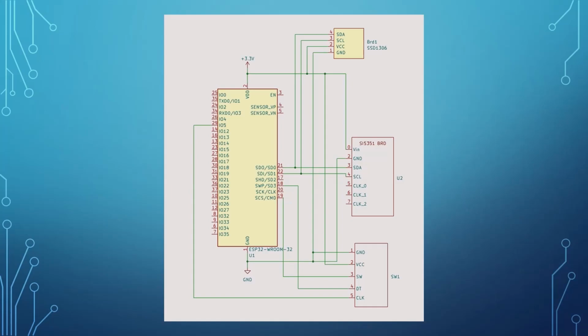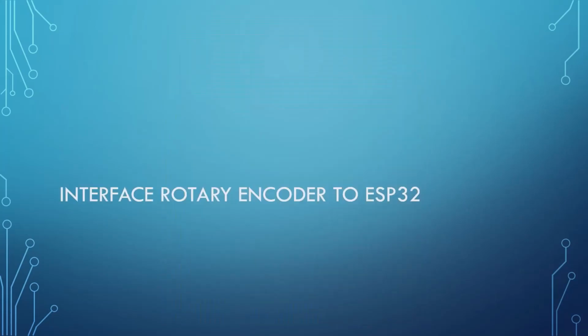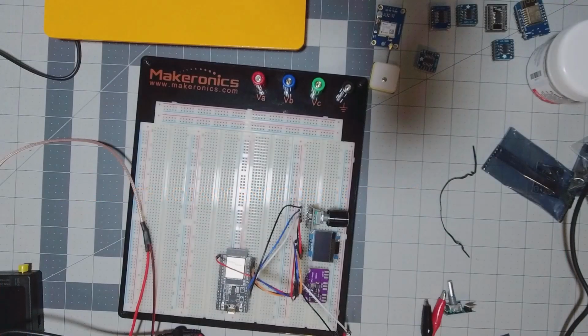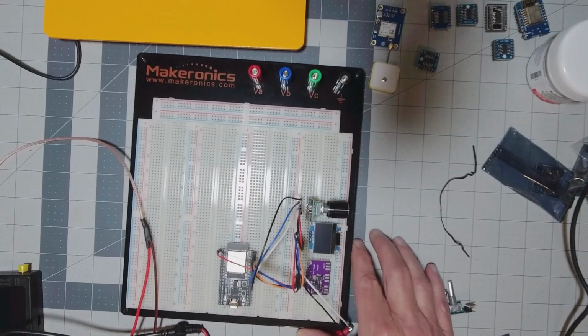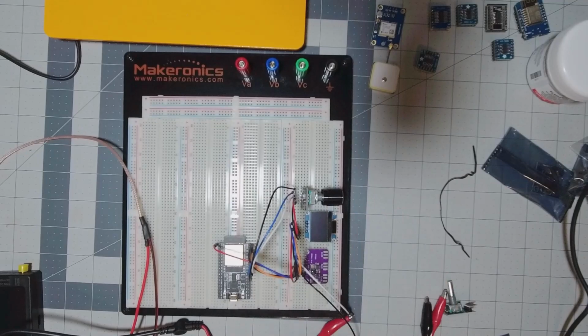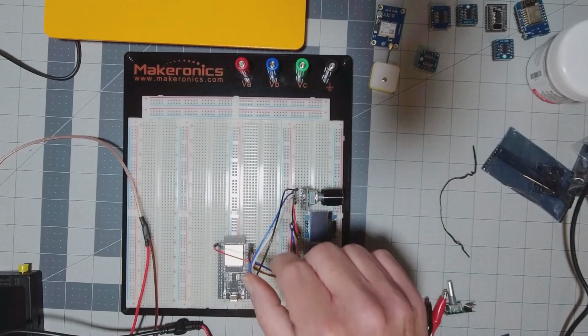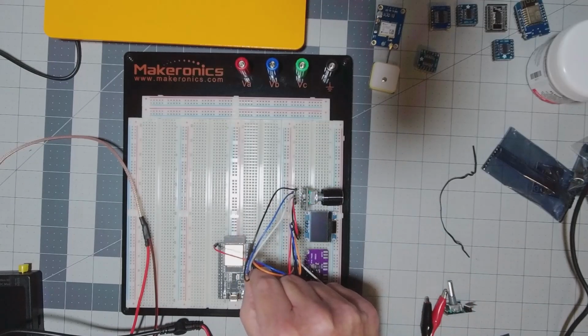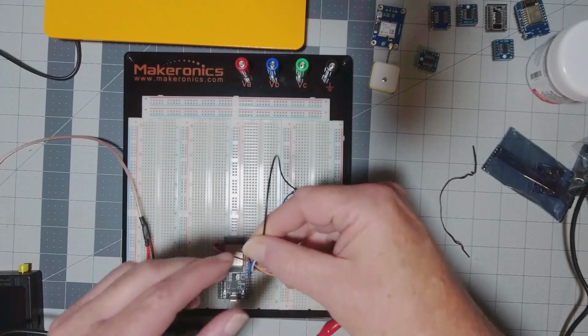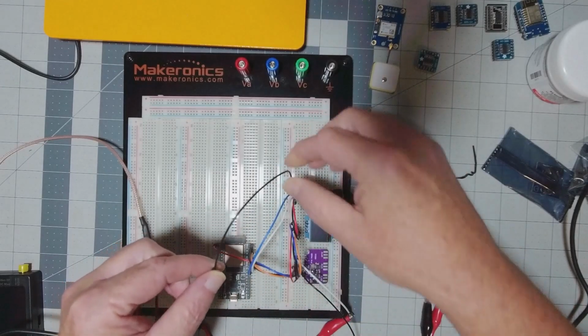I guess what we'll do here is, let me get my overhead view. You guys should be able to see that. What we're talking about are these 3 pins here. This is GPIO 5, and I'm running that to the very last pin over here.